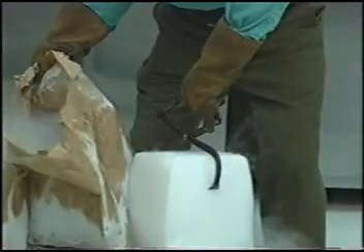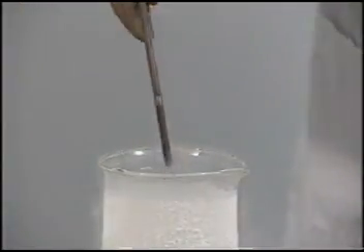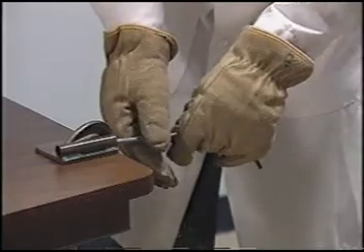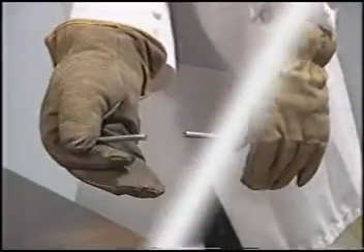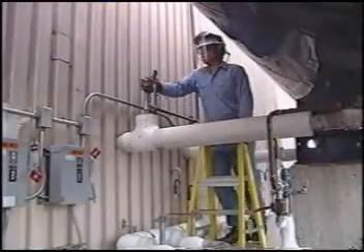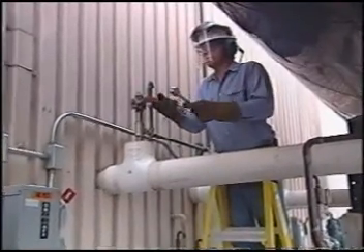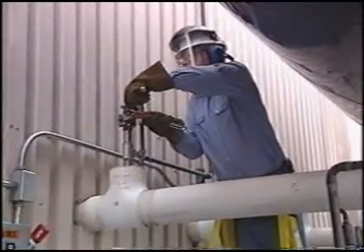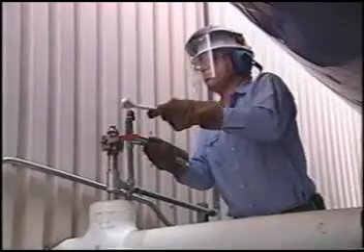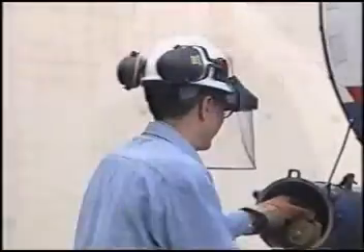The third potential hazard is handling carbon dioxide at extremely low temperatures. For example, carbon steel pipe loses its toughness when it's cooled far below ambient temperature. It can break or even rupture under pressure if it is hit or even torqued with a wrench. Contact with pipes that contain carbon dioxide also can freeze flesh. Make sure everyone working with or near these cold pipes wears long-sleeve shirts and insulated gauntlet gloves.